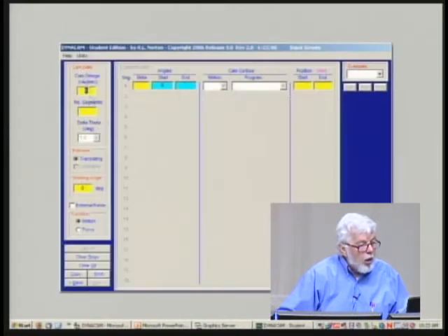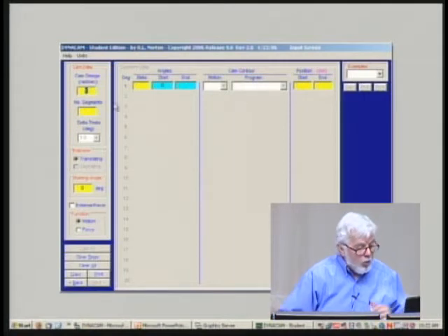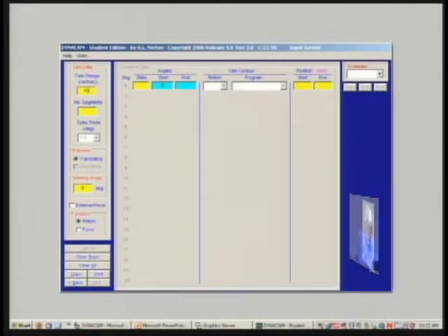I'm going to go to the SVAJ screen. If you've seen the tape on the 4-bar program, you know that yellow boxes in these programs are for input and the cyan are for feedback to you. So I can type in any yellow box, and the first thing I'm going to put in is the speed of this thing, which I think was 10.467 or something like that, radians per second.